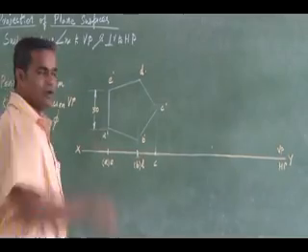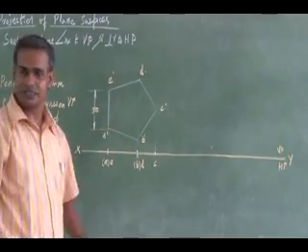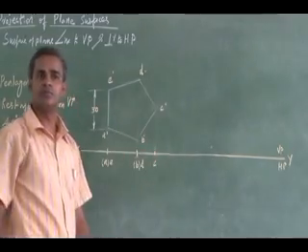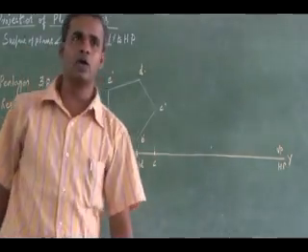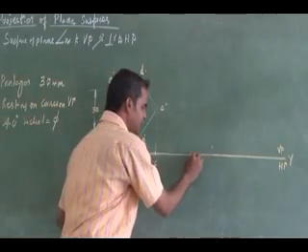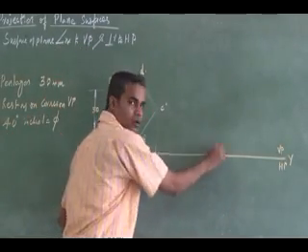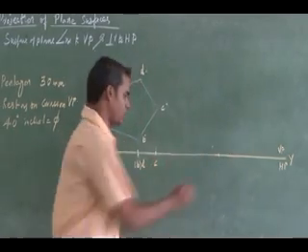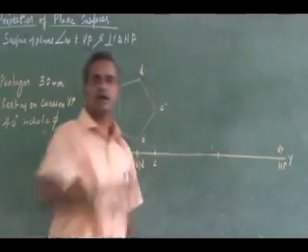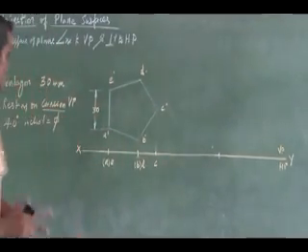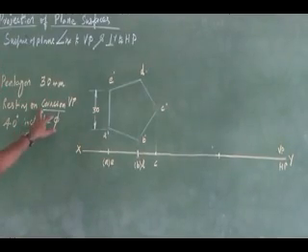Right. Then what do I have to do? I have to tilt this. This is going to be the final top view, and I have to tilt it to 40 degrees. Now the question is which one I have to keep here. Either it is resting with a corner or resting with an edge. It is resting with a corner.